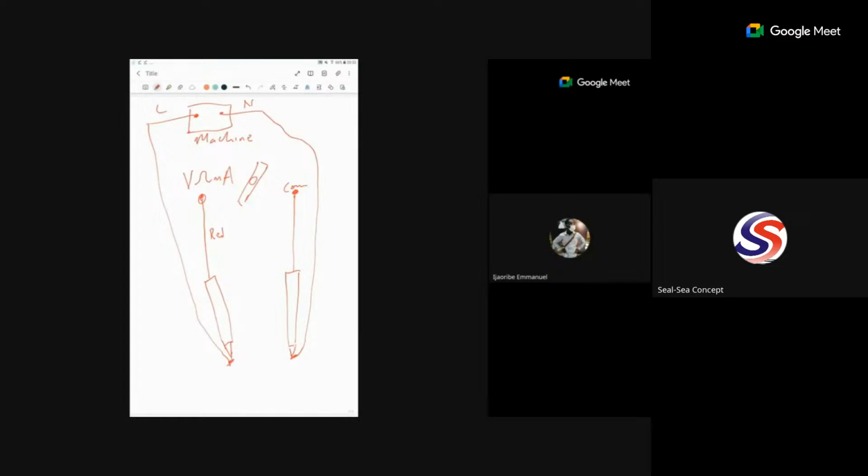So you put it here, and then if it's your digital or your analog, it will display the voltage in the system. Now, when you are testing for voltage, you should know that testing for voltage is done on a live circuit. Live circuit means that the system is powered. It has to be powered. Okay, so you don't test for voltage on a dead circuit. You test for voltage on a live circuit.